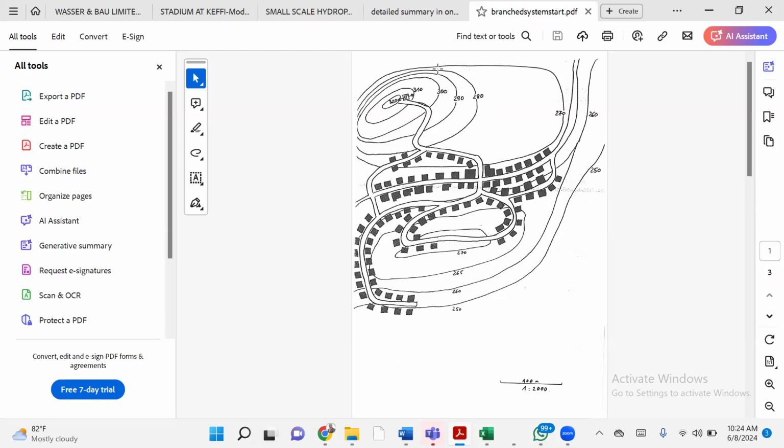And we said that your network must not be more than 8 bars based on German standard anyway, which would also apply here. Once the head difference between the water source and the lowest point in the network is more than 8 bars, then you need to provide pressure zones, or you need to provide a cascade, or you need to provide buffer tanks. You need to have a way to cut off the pressure, break the pressure. And of course, you know how we break pressure. You just create a reservoir midway, okay?